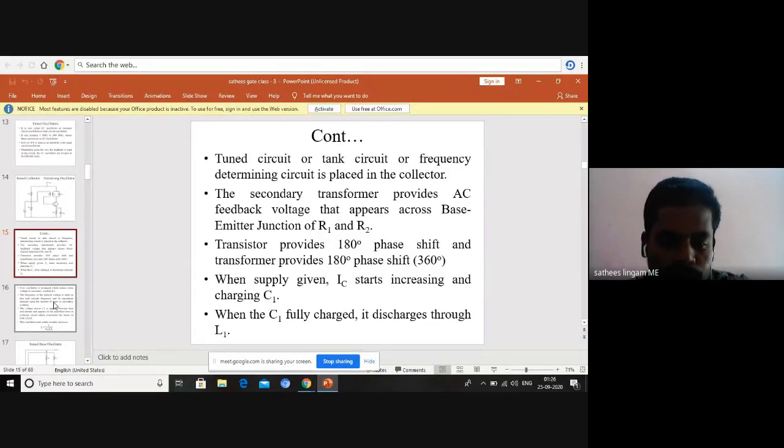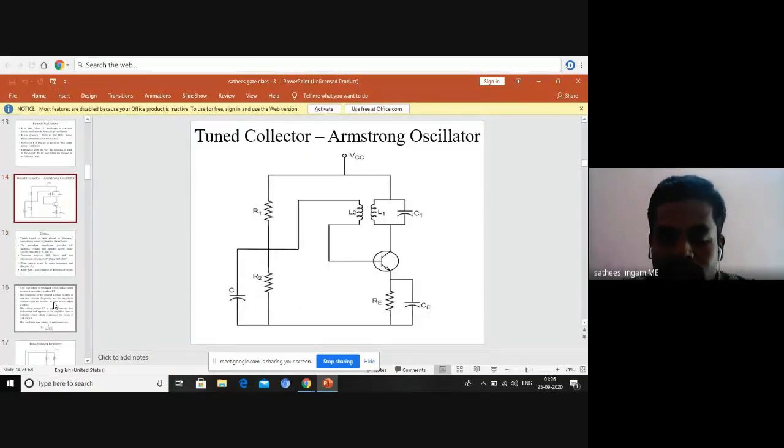Output of the inductor, we are receiving that, and it is looped into an amplifier. The amplifier is doing the amplifying operation, so that the base of the transistor is receiving the oscillation signal. That means the oscillator signal. The oscillation is created by C1 and L1. You got it? Then the output we can see in our amplifier.